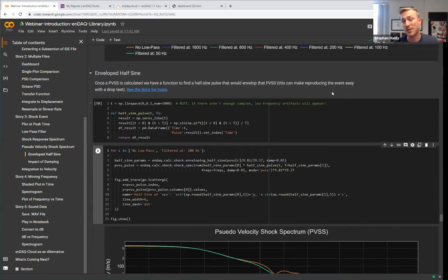I compare acceleration data from an earthquake to a gunshot. And the earthquake has really low amplitude data, but that's a lot of energy that can really break buildings and tear apart various systems. But if you only looked at that time domain data, you'd see there's no damage potential in this data set. But that's just not true. And you need to take into account the frequency content too.